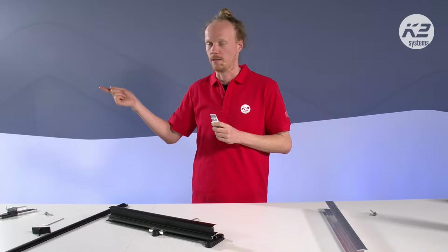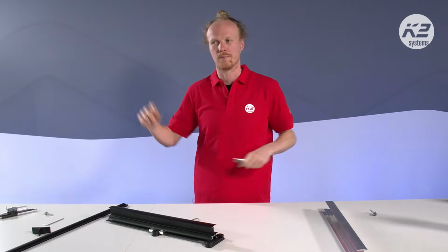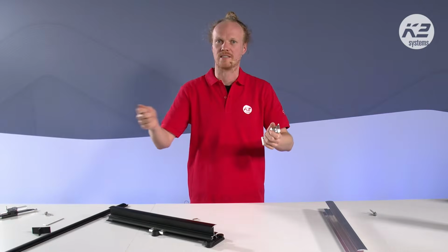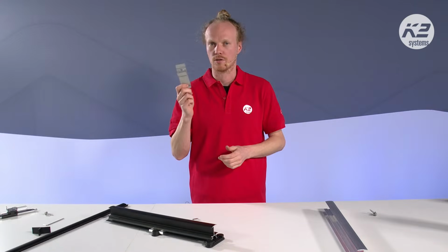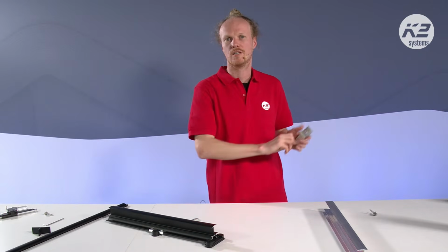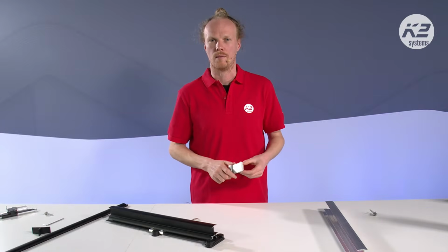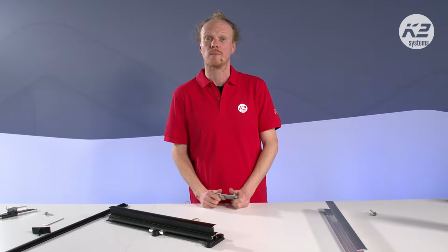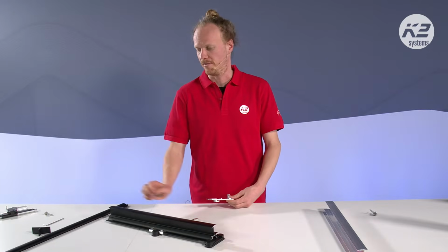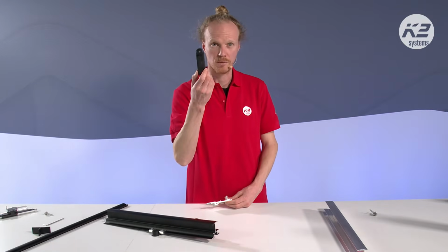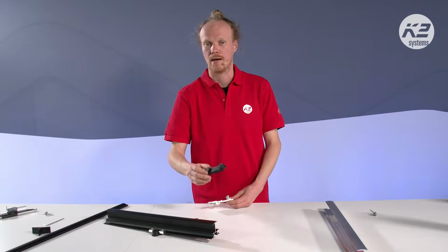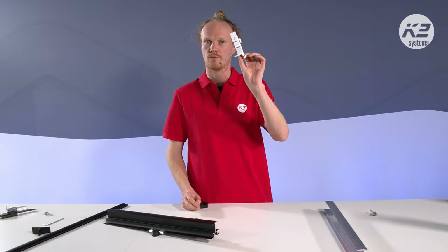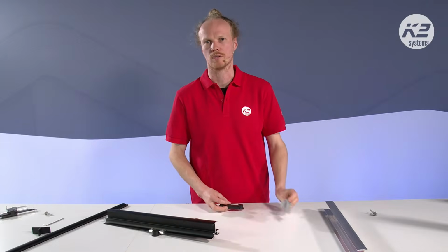With the basic clips, you can put the first basic clip and the last basic clip, and then you do this up-down function, and you're done, and you just fix it. But with the cross connector, you actually have to align them all first. So you are going to spend a bit more time doing the installation as well. And as Vlado said, the material will be extra, because instead of having this product and 2 screws, you have 25 centimeters of rail, 4 screws, MK2, this product, and so it just becomes a little bit more as well.